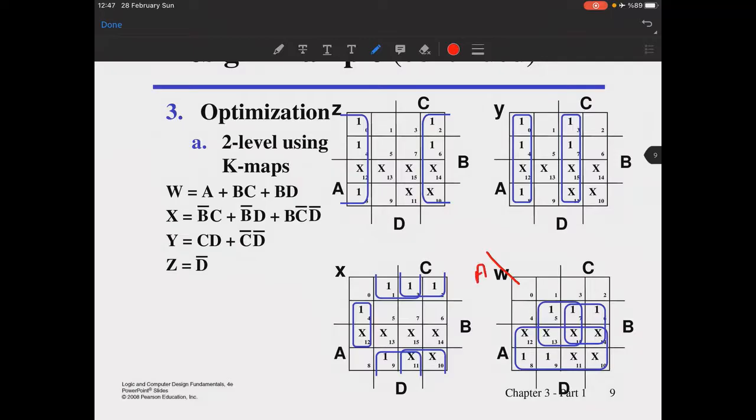You should remember that this is already labeled for us. You see, it has the labels. But this is how we make the positioning. A, B, C, D are located like this in our truth tables. Now we do some optimization. What was K-map optimization? We're trying to get the largest possible rectangles here in sizes of powers of 2.